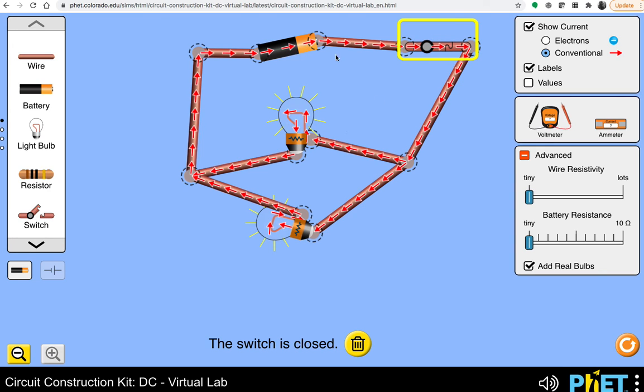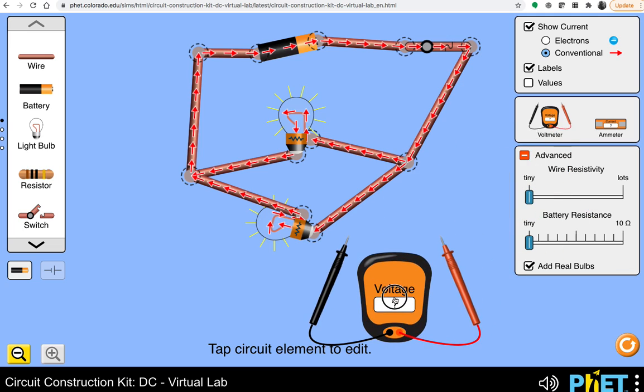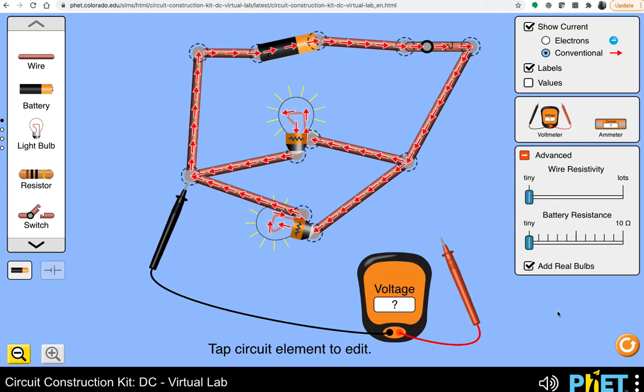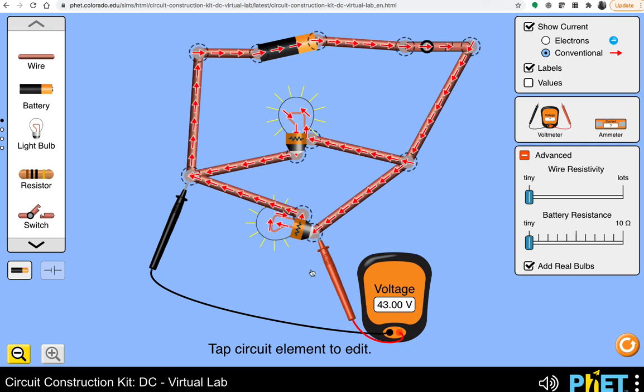Okay, I'll connect it, and if I want to, I could again measure the voltage on this junction, this one if I need to, or in this light bulb. Right? So when you measure voltage, you measure voltage on everything that is connected in between these 2 points. So in this case, you're measuring just this light bulb. Okay, so that's it. Again, you can look at different parts and elements here. Remember about where to measure and this advanced section.